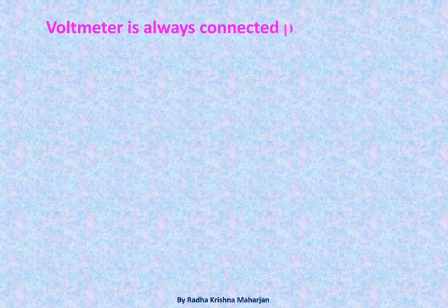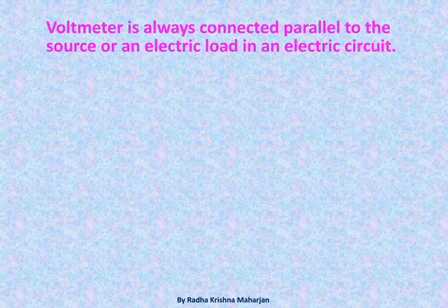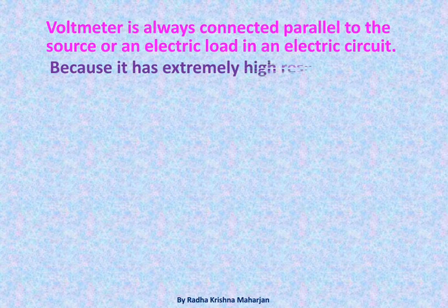Voltmeter is always connected parallel to the source or an electric load in an electric circuit, because it has extremely high resistance.